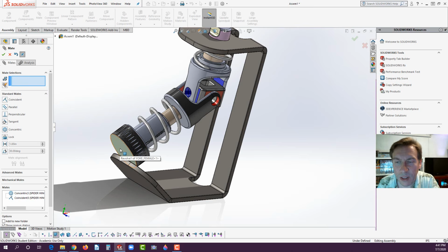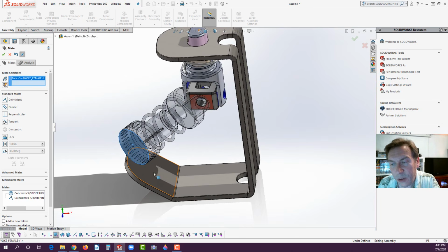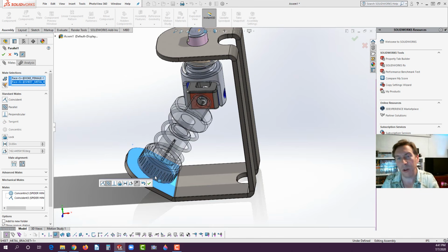Okay, now select this pale green surface on the underside of that plunger. And then go ahead and select this surface right here. And notice on the left, it actually selected parallel. That's one it hasn't done yet. It's done coincident. Coincident is face-to-face contact. Parallel allows it to align itself, but at whatever distance it is. So parallel is a very useful thing, and SolidWorks AI automatically knew to do that.